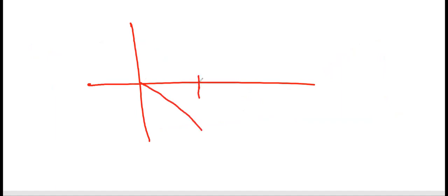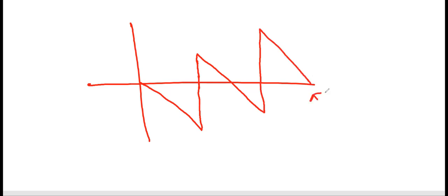Number two is the phase response. For our case, the phase response can be negative or positive. So we should go like that. And whenever we have a crossing in the magnitude response, we need to jump 180 degree shifting, and then we move again. If there is a crossing in the magnitude response, we need to shift again by 180 degrees, and we need to stop again just on the pi value of the omega scale.